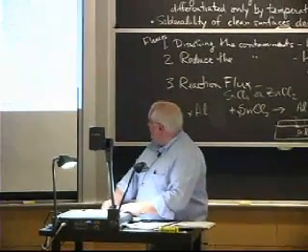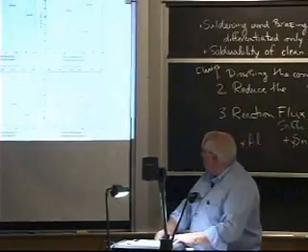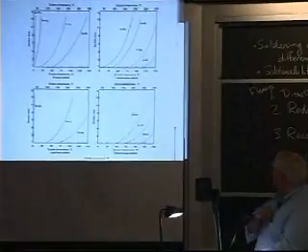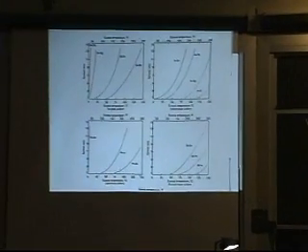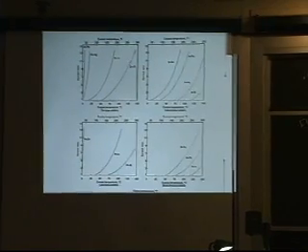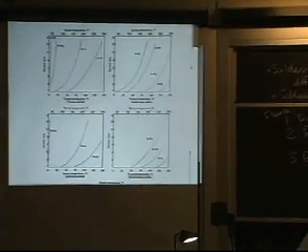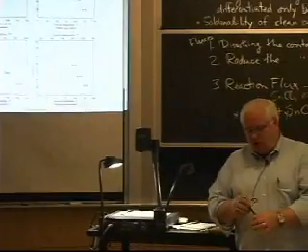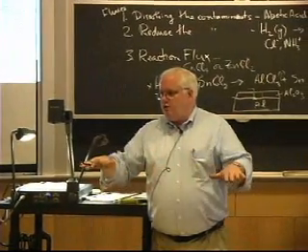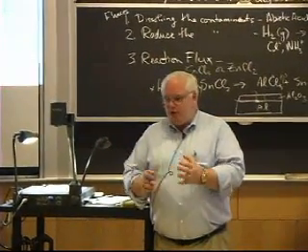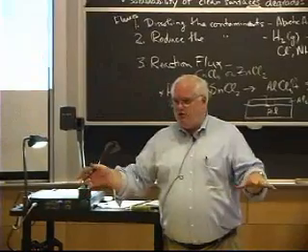We talked about spreading. You need to have spreadability of the solder. And these are different solder alloy families in terms of what they call the spread ratio. For the spread ratio, you just take a little ball of solder and you put it onto whatever substrate, if it's copper or nickel or whatever you're soldering to. And then you heat it up and you see how far it spreads out. It starts out at 1 diameter as a ball and it spreads out to a pancake. What's the diameter of the pancake?